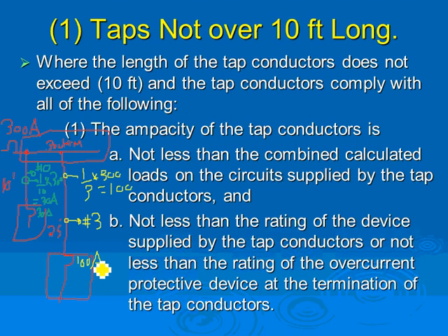Oh yeah, I can come here. That's not a tap. I can take 30 amps from here and feed this a load conductor, number 10. No problem. But you couldn't make that a tap. It's a circuit off that breaker. No, you can't tap a tap. It's already tapped.